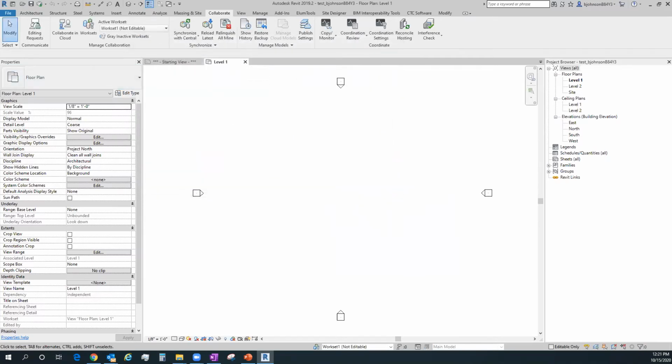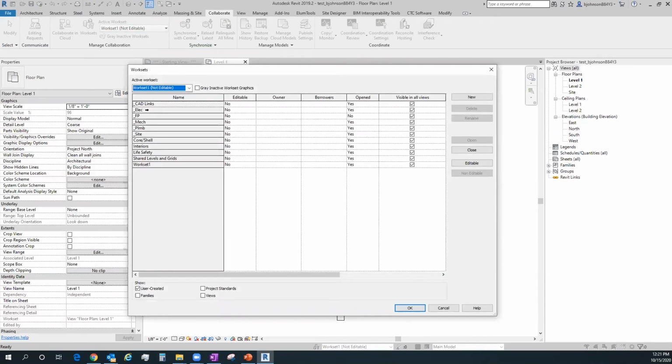I'm trying to think if there's anything else I need to do here on the setup side. I also usually have area worksets on very large building projects. If I had multi-building, building 1, 2, 3 or A, B, C, usually my worksets would also be included here, with building 1 electrical or area A electrical. Again, like 1,000,000 square foot plus industrial projects, things like that. Those would be areas of concern. We have multiple areas for worksets where you can turn off specific areas of the building all at once, as opposed to having simpler workset designations.